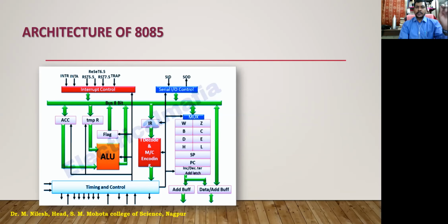So that address is to be given to the microprocessor, 6000, and we push a button which is called execute. So it starts to execute from 6000. The first address is stored in this program counter. Then it executes the first instruction. The next instruction is in the next memory location, so it keeps track of the program, taking the next memory location each time. It keeps track of 16 bits. So this program counter and the stack pointer are 16 bits wide.